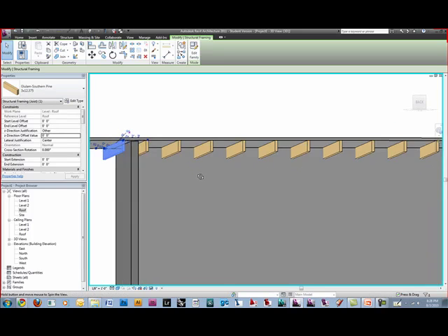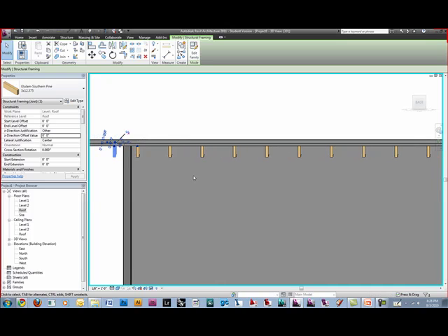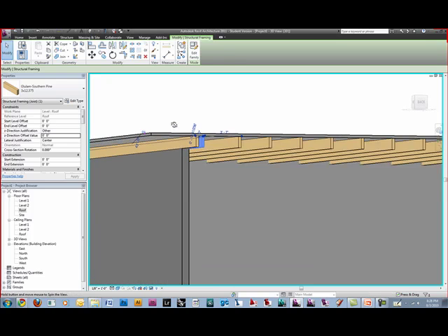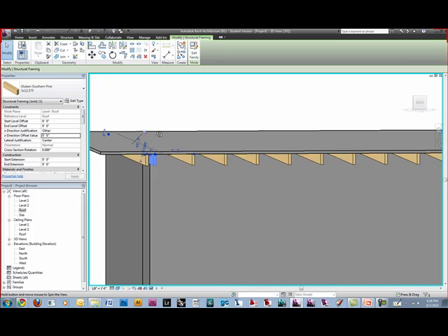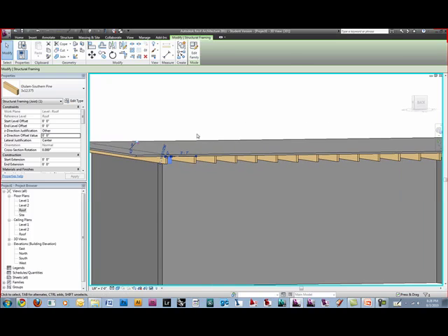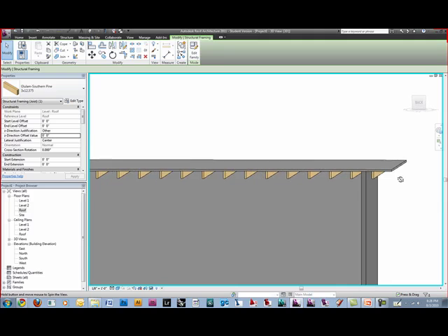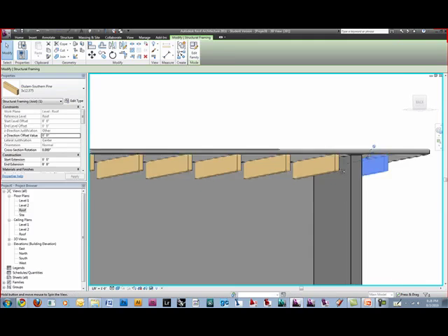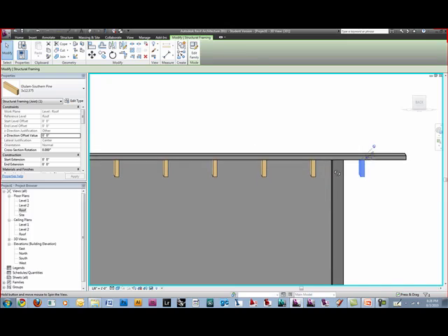These pinned objects are everywhere in Revit, where it's creating its own system. That's curtain systems, grid systems, anything like that. It's all pinned. So if it says it can't move because it's pinned, then find the little pin, the little thumbtack, and just click it, not uncheck it, and that way you can move the stuff where you actually need it to be. Don't let Revit tell you what to do. Yeah, it'll restrict you. It's my beam, put it where I want to. You can do whatever you want.